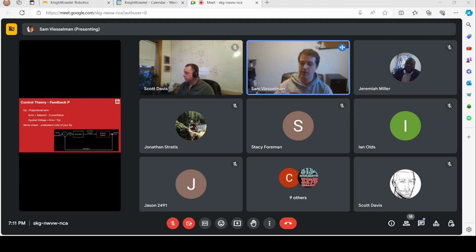So if I just break that down really fast, let's say I have a Kp of 10, and let's say I'm trying to run my flywheel at 80% speed. I request 80%. My sensor sees that I'm only at 78% speed. It's going to take that 80 minus 78, which is 2%, and multiply it by my 10, and that's how much extra voltage it's going to apply.